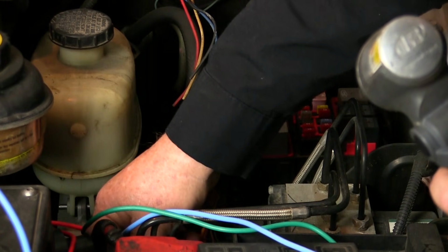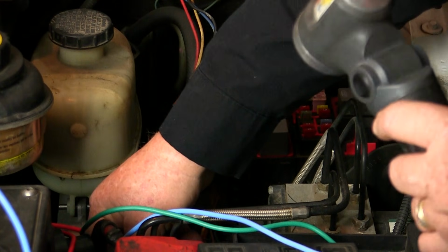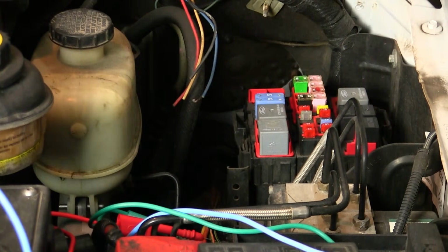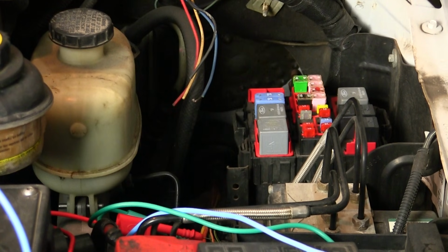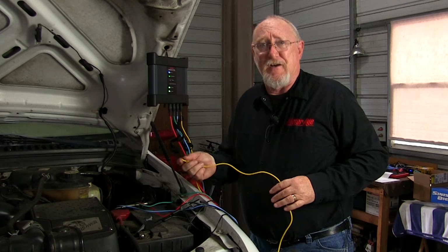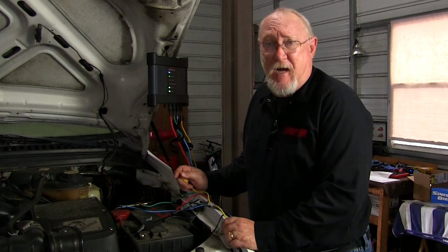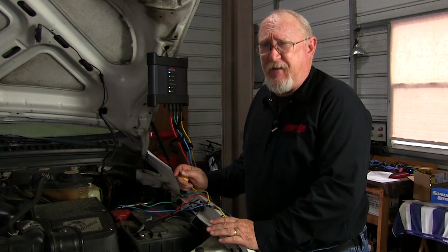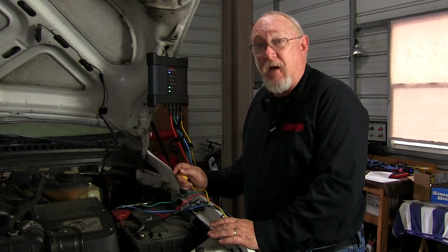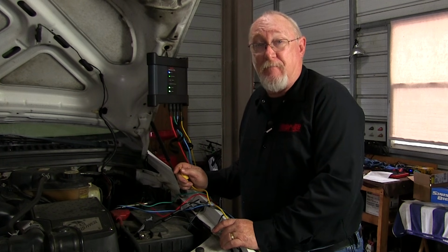But I am going to assign a channel to the fuse at F1.11, the 10 amp fuse that is only hot when the key is in the run position. And that's going to leave channel 4 to monitor the CAN signal at the module. If I see anything funky going on, it'll be easy enough to move over to the other signal wire and monitor both at the same time.